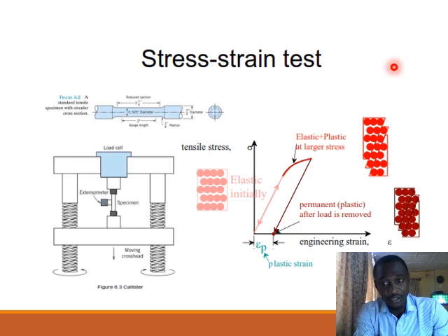If you know those mechanical properties, they will guide you in understanding your load application during operation. So I give you a typical example. If there's a mechanical property called, say, tensile strength, you need to know what it is. If you know the tensile strength, and you are going to put the material through a tensile load and you don't want it to fail, then the resulting tensile stress from that load must be less than the tensile strength of the material.